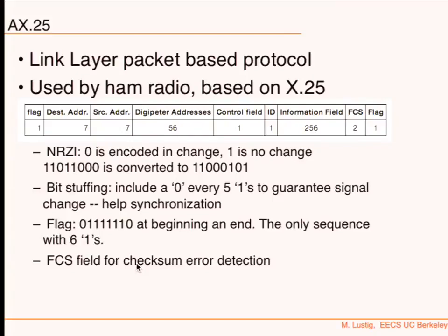Every layer needs to look down and up and create things that are easy to implement. That helps a lot, and you'll see that in the decoding. The fact that you use non-return to 0 inverted helps a lot. The fact that you have the synchronization helps a lot.